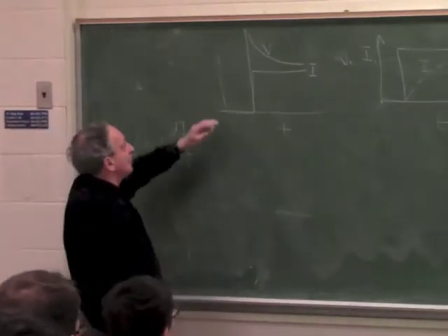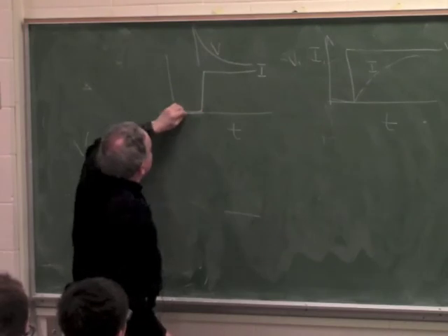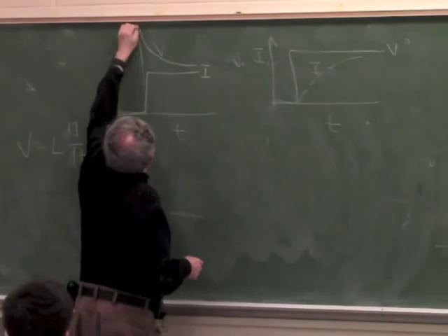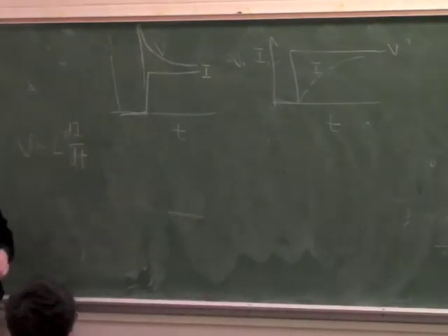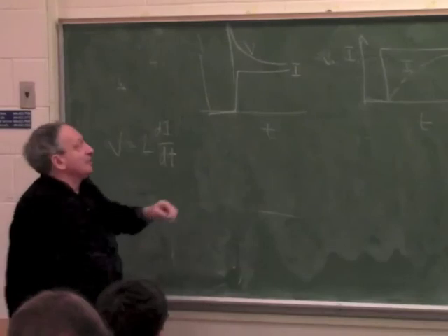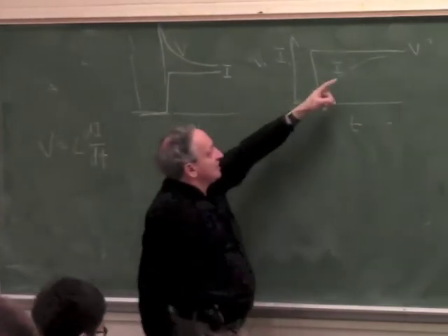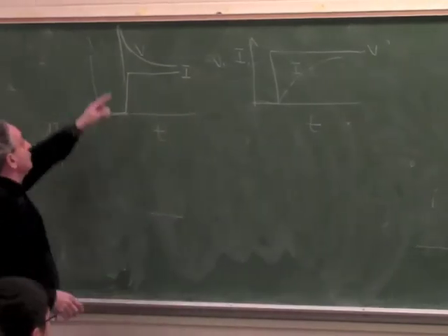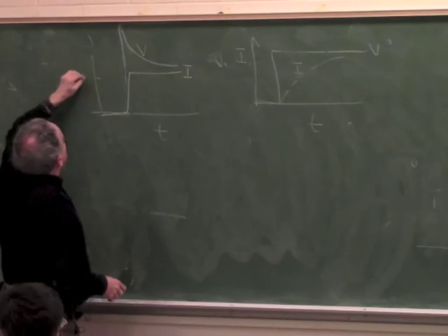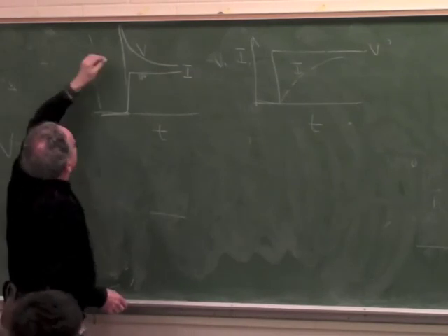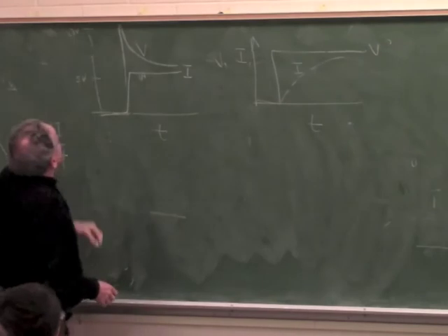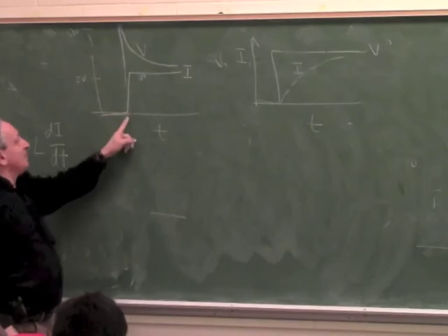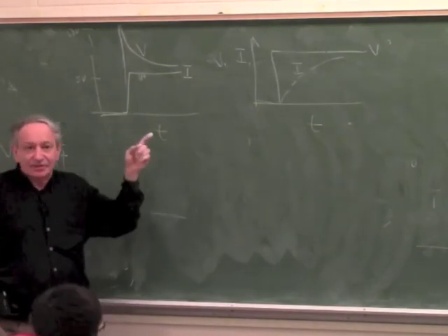So what you do is a compromise. You make the I with a certain slope, a pretty fast slope, so the V doesn't have to start from infinity, but starts from a very high voltage. So for a typical drive of a stepper motor, if the working voltage is, let's say, 5 volt, you actually start with 50 volt. So say this will be 5 volt, and this will be say 1 amp. You'll start with a 50 volt drive, so it will be almost like constant current. Okay, so this will give you a much faster rise time. Is that clear to everybody?